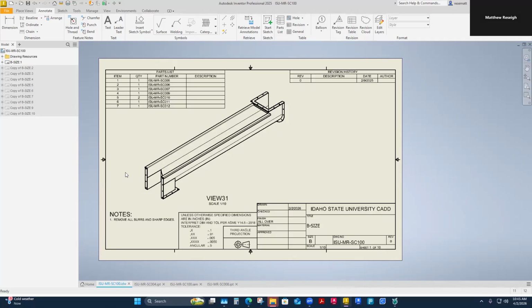I put the end plates on it, and maybe some stiffeners. We maybe need to add some supports along this 8 foot span to hold that U shape of my conveyor, because sheet metal is flimsy. And I've talked about how you can bend sheet metal to create stiffening. I can also add some external 3/16 U-shaped parts that will become stiffeners, is what we would call that, along this length from inlet to discharge. The inlet and discharge are going to be a pretty rigid structure by the time we bolt on the end plates.